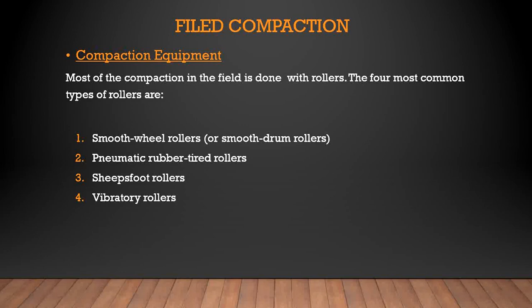Soil compaction or densification can be achieved by different means such as tamping action, kneading action, vibration and impact. The compactors operating on the tamping, kneading and impact principle are effective in the case of cohesive soils, while those operating on the kneading, tamping and vibratory principle are effective in case of cohesionless soils.